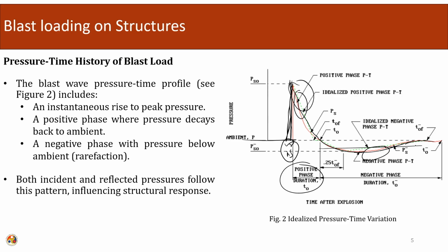phase. So, the signature consists of an instantaneous rise to peak pressure, a positive phase where pressure decays back to ambient. So, there is decay and it goes back to the ambient, and after that the suction or the negative phase occurs, and after that it subsides to the ambient.